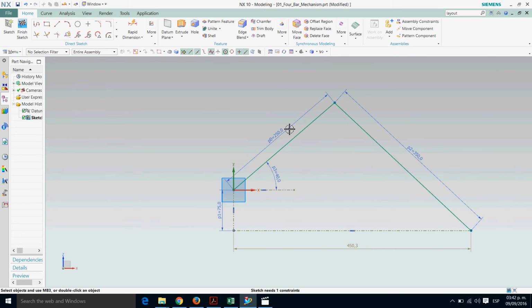That's it. Now let's create several circles that will help us to create the center of gravity and all the joints we need to use for the mechanism. At 0, 0, we create one circle, and the midpoint.